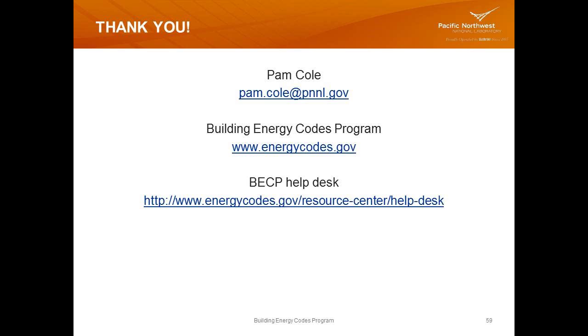REScheck uses the equivalent U-factor table, and that's different, but it does require that heated slabs have insulation underneath the entire slab. This is now code-driven, because you're going to have heat loss if you have hydronic heating, and the intent is to prevent that heat loss, because you have that hydronic system in the slab, if you are in a climate zone that requires insulation. So I probably didn't answer that one completely for this person. If not, they could submit the question through the help desk, and we can get more specific for them.